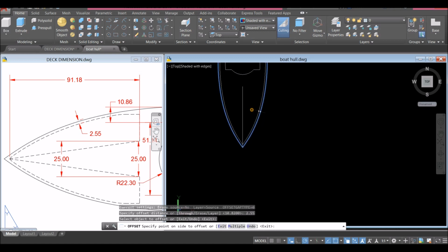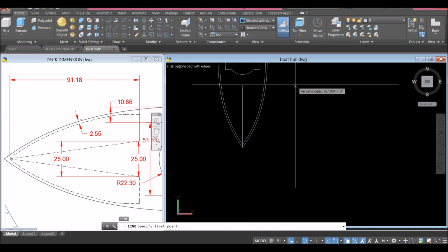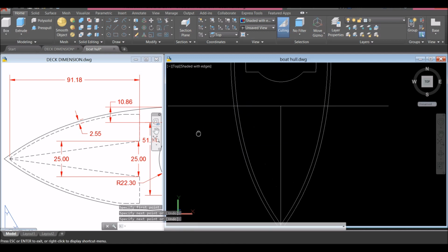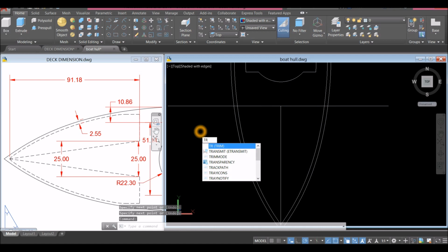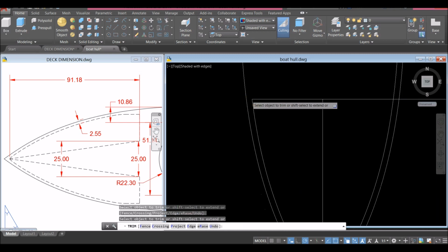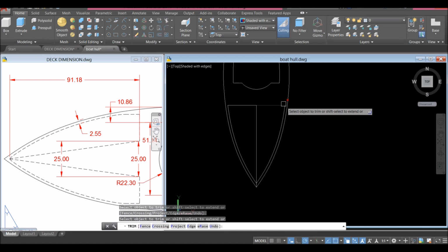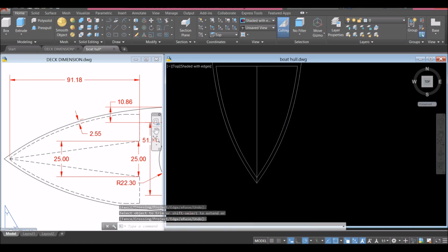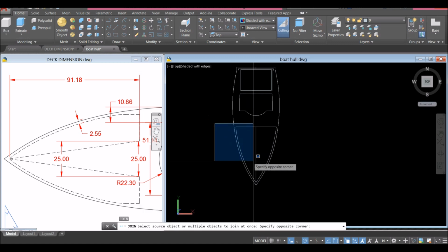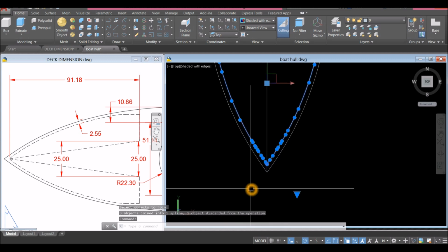Click this one and click inside and draw a line. Just hover over, move to the side, click starting from here, anywhere here, and trim. So TR for trim command again, enter twice, cut this one here, this one, and join the segments by typing J for join command, and just window the whole thing from the left. And this is now one object.